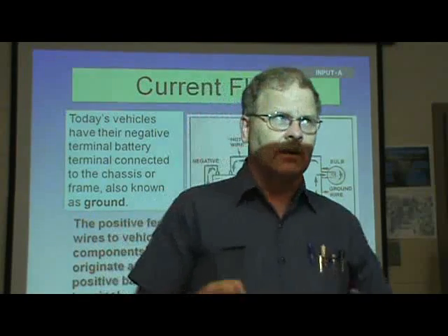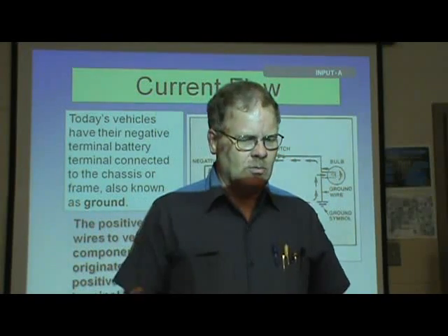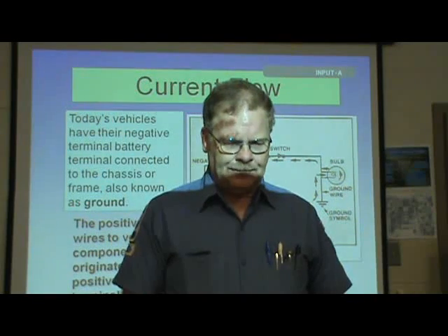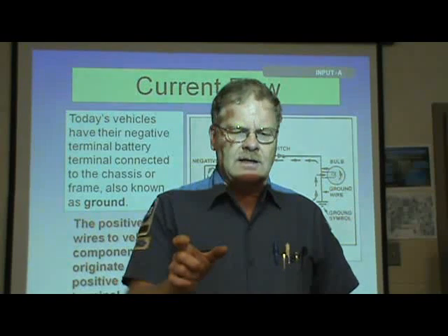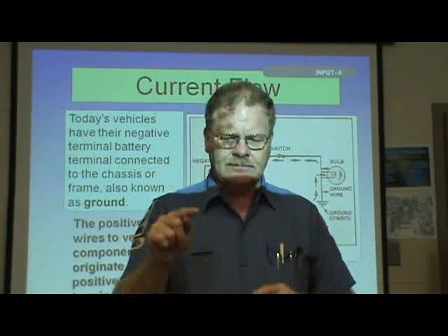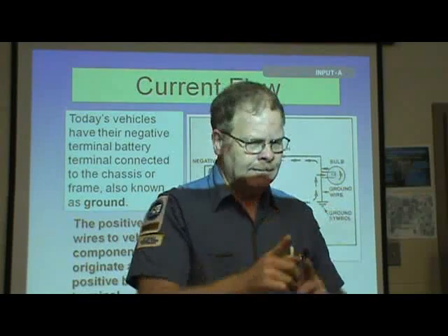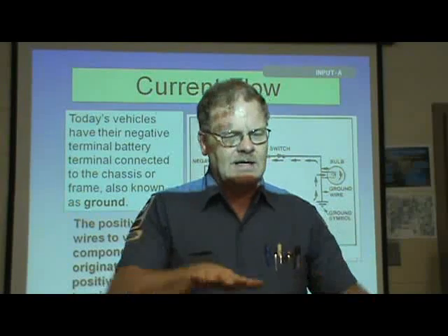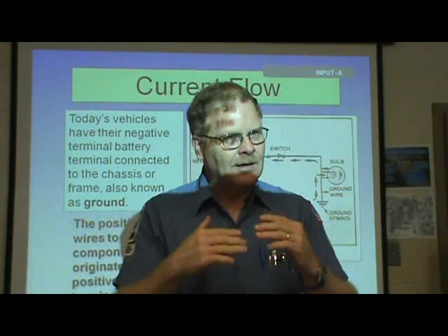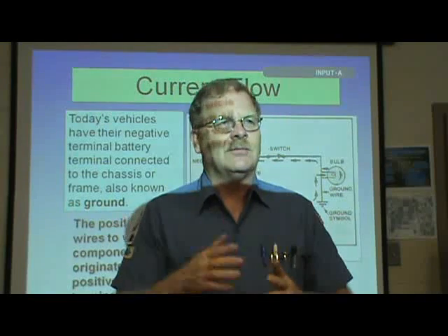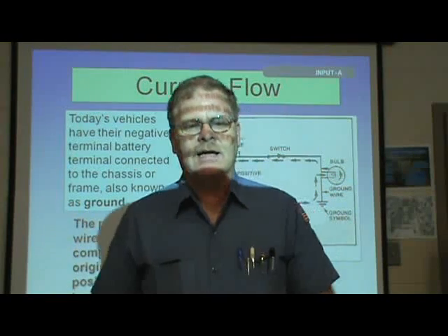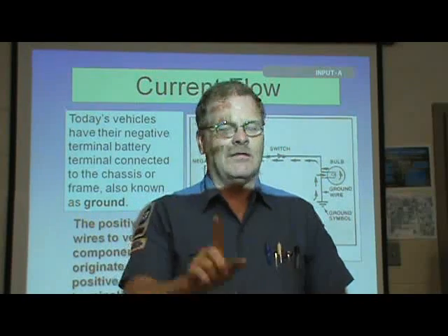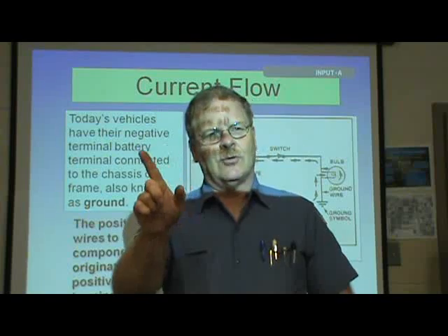We used to have these motorhomes that would come in here, and the motorhome was basically an F-53 chassis with a motor coach put on it. These people would take big, heavy, double-aught gauge wire with heavy copper on it and run it straight from the frame to the engine. Not that far. Over time, every time the engine torqued a little bit, it would eventually break that terminal. And when that terminal eventually broke, so that you no longer had a good ground between the engine and the body, on that particular kind of vehicle, when it would drive off, your temperature gauge would go toward hot.